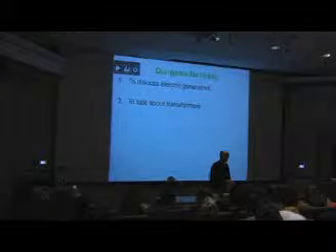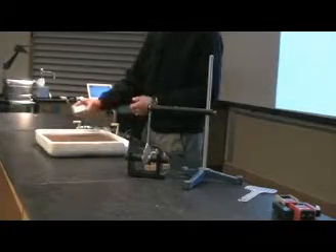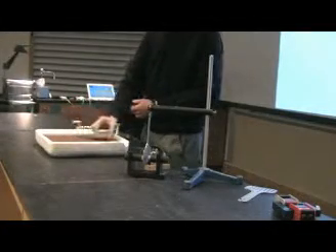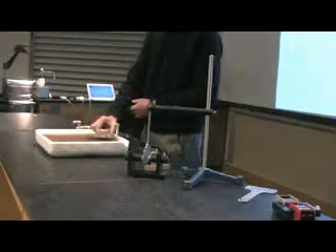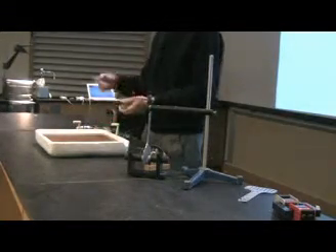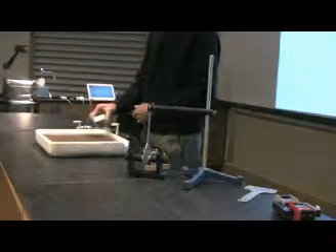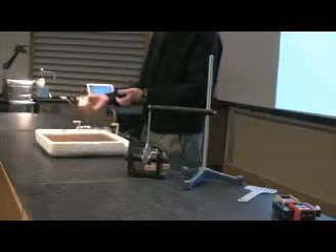I'm moving the magnet around, so I'm changing the flux through the copper. So you're creating an induced... And so there are these induced eddy currents in there. Exactly right. This sounds great. So changing the flux in various parts of the copper induces eddy currents. And the eddy currents, what they do, they create a field. Eddy currents are swirling currents of electrons. And they create a field which acts to oppose whatever's producing the change in flux.